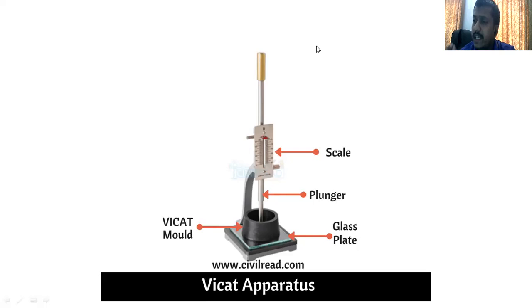Because only in this test you will come to know how much quantity of water you are going to add to make a good cement paste. Once you know the consistency, the rest of the things are very simple for you. That is why consistency test is very, very, very important.